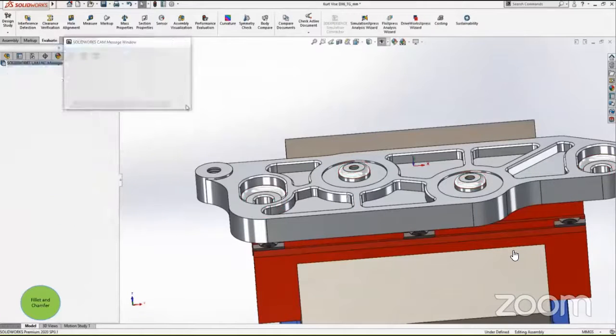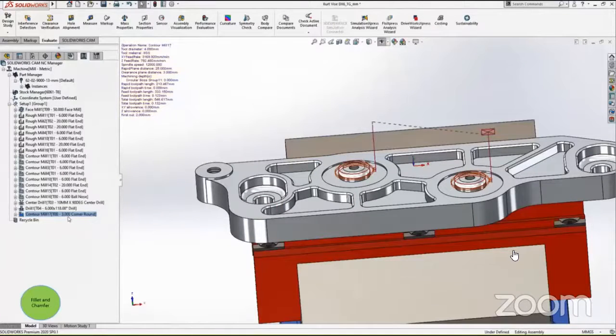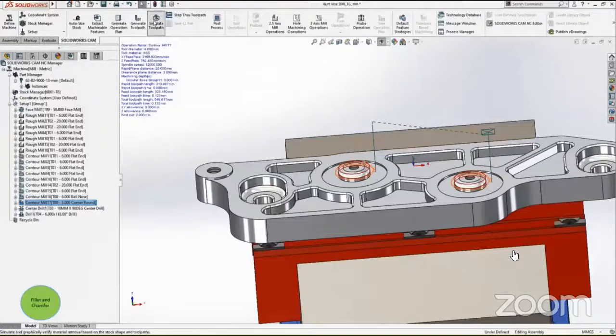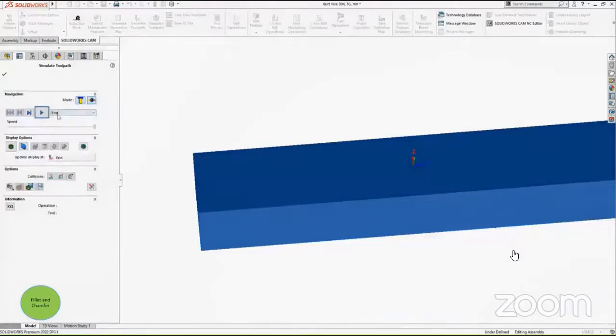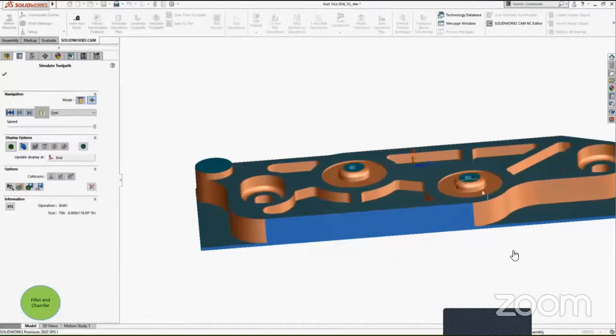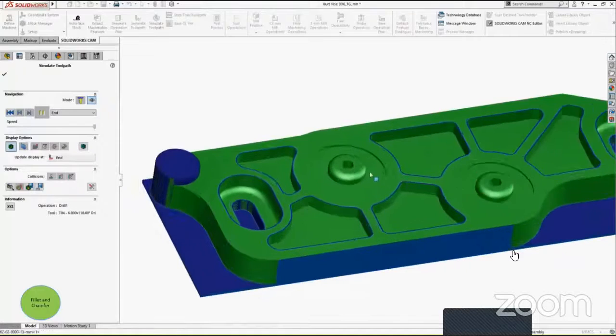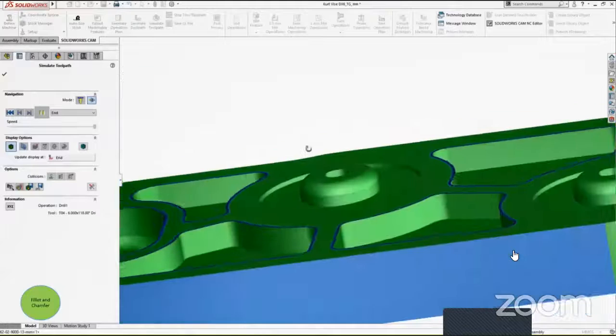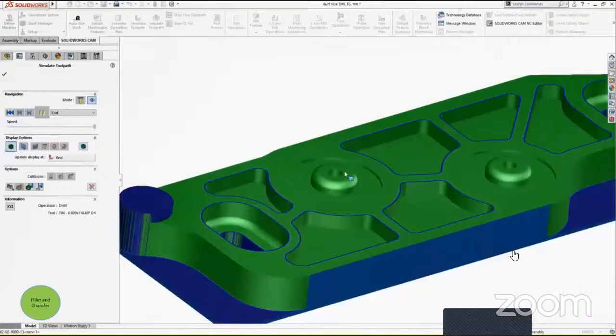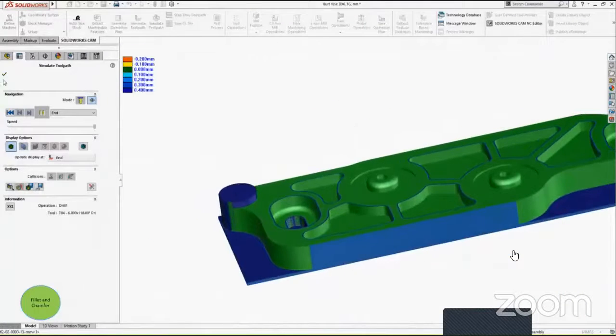Now we will generate the tool path and then drag this one under the control milling section. So let's simulate the result and see what we get. We use the turbo mode, and there we go. Here we have the corner fillets. If we select the show difference option, in color form, we can see the green color shows it is precisely what we have after machining, and it's completely matched with the CAD file. That is great.